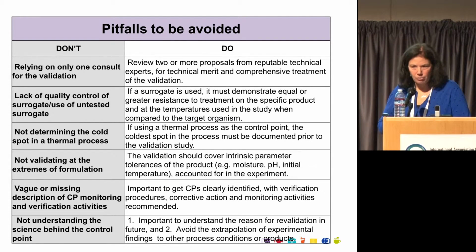The validation should cover intrinsic parameters, tolerances of the product. So if you validate at 3% moisture, don't accept a product that's 2% moisture because that will make a big difference in how the Salmonella is reduced.